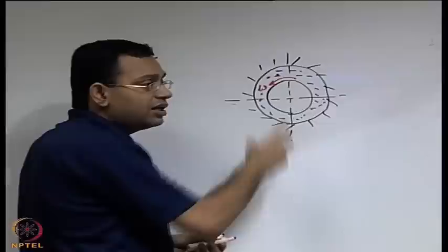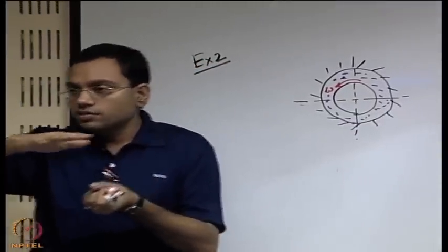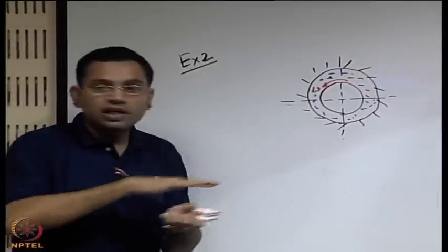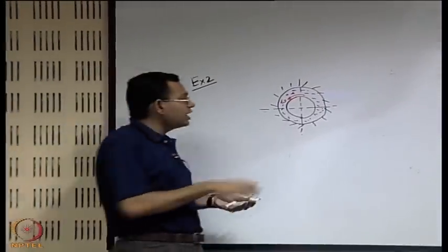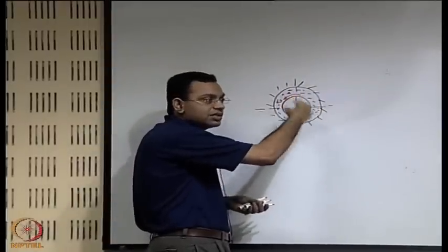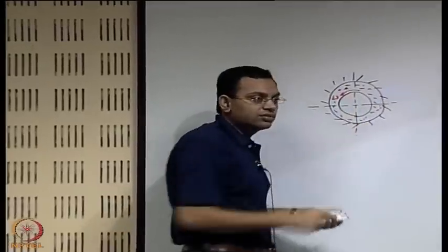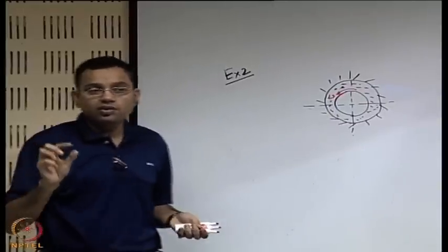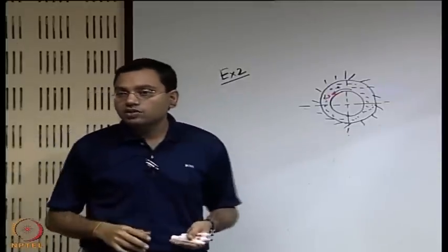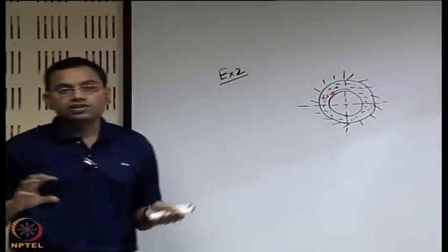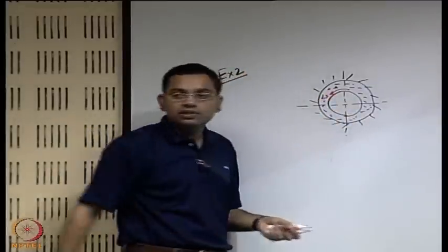That shaft is rotating, but it has to be housed in a certain position. At the same time, if you constrain it with a direct metal to metal contact, that will give rise to a lot of wear and tear. So, there is a lubricating material, typically an oil, which separates it from an outer housing, sometimes called a bearing, and the whole idea is to create a lubricating layer in between these two, which prevents the wear and tear because of the metal to metal contact. So, the shaft bearing type of arrangement in industry is very common, and that is where you will find a lot of application of this kind.